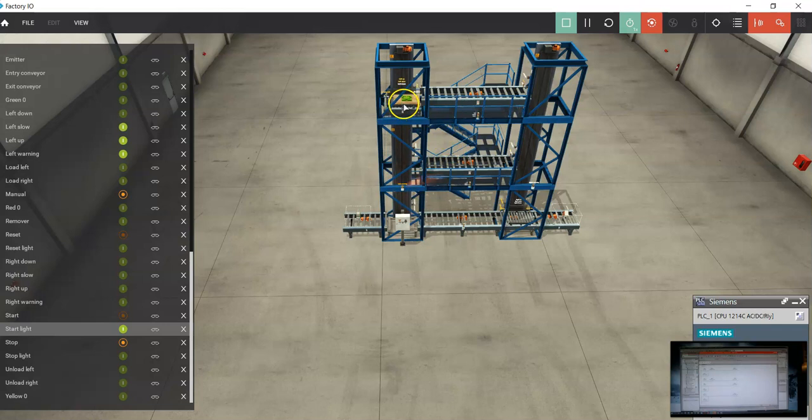And again, as soon as the pallet is fully onto the conveyor, the right-hand side will start to move up to try to retrieve it. Now, you can actually write the program so that, since right now we're just alternating levels, you can raise the right elevator at the same time as the left elevator, so then you can catch the pallet as it's coming across. Now this one's a 0, so this one's just going straight across.